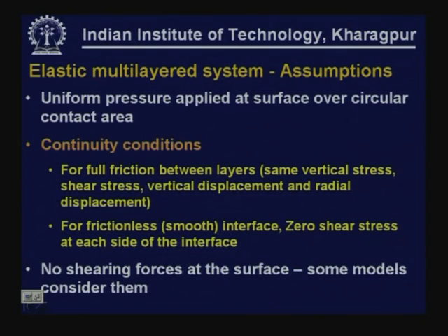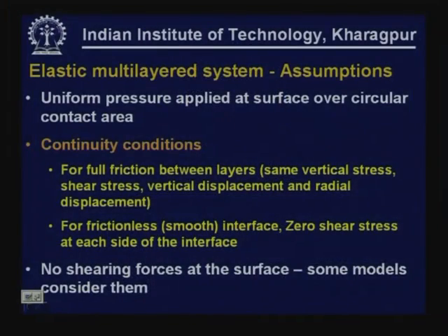We assume full friction and full contact also. We can also analyze the pavements for a frictionless interface, assuming that the interface between different layers is smooth, that leads to zero shear stress at each side of the interface. We normally do not consider shearing forces at the surface, although some models are available which are capable of analyzing pavements for surface shear forces.